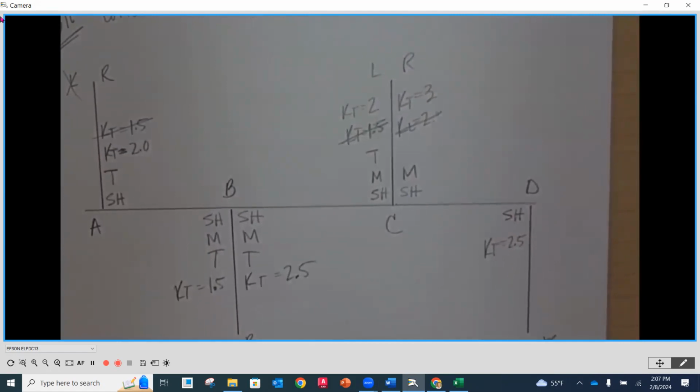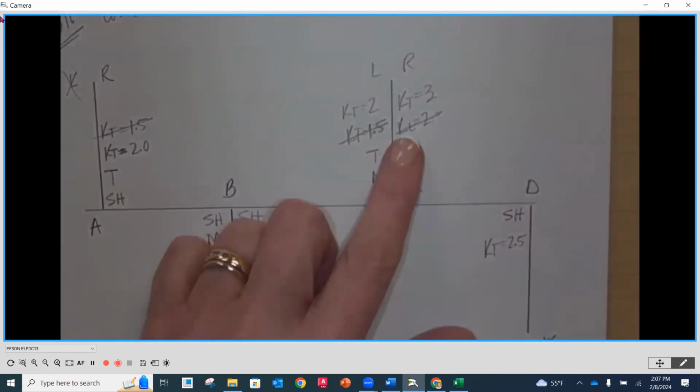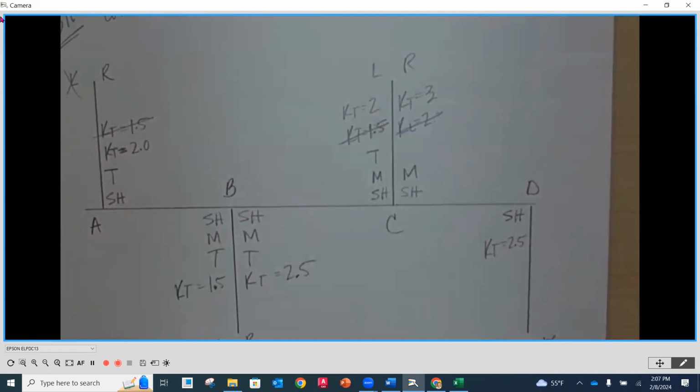Does that make sense to everybody? That's why we can't let any of those radiuses for our keyways extend beyond, even if we're not using them. Otherwise, we're going to have really high stress concentration values, and now we have to bump our diameters up needlessly. If it's something that you as a designer can control, you want to.